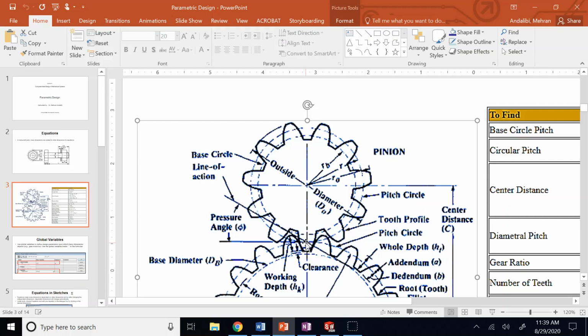The only two circles that touch each other without intersecting or being completely separate are the pitch circles, because the dedendum circles never touch each other. There is also another circle called the base circle, we'll talk about that later, and that base circle also never touches. It's very close to the dedendum circle. The pitch circles are tangent to each other, and then the addendum circles will basically intersect at two points.